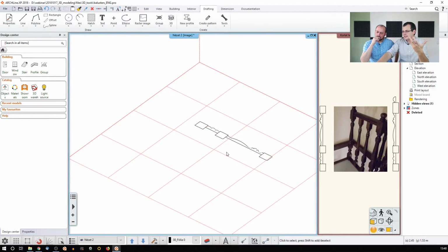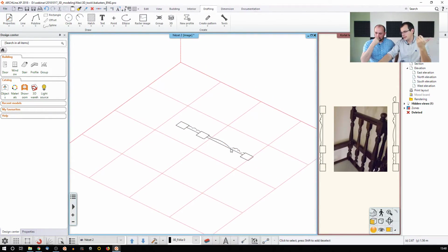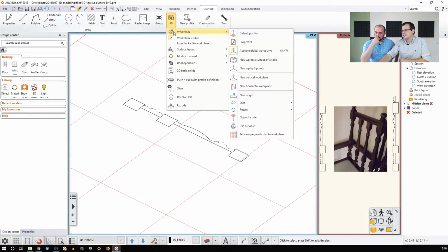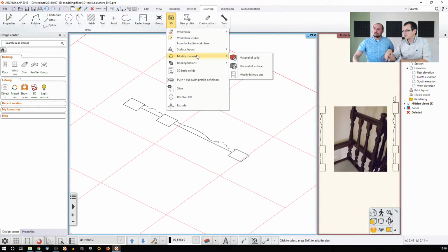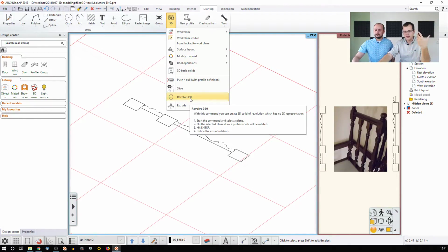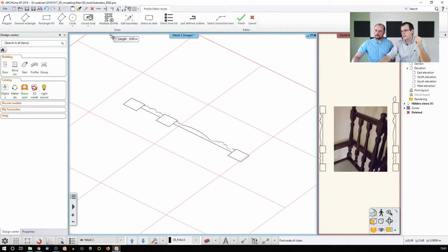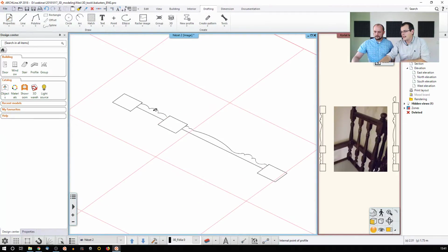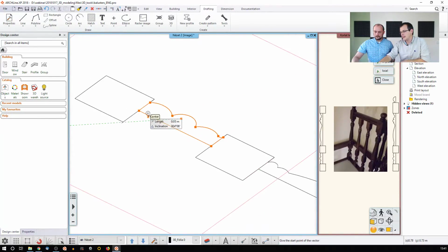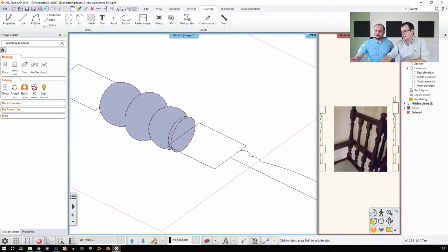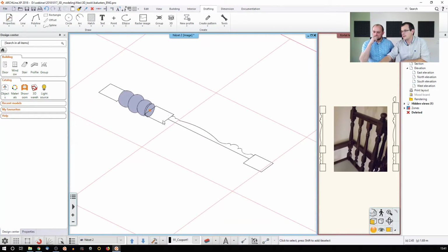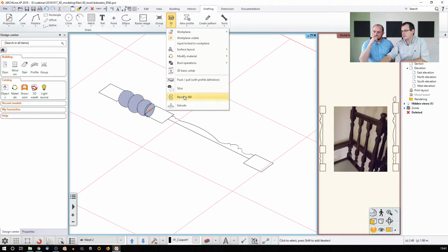And now the next task is to turn this into a 3-dimensional object. And I do this with these tools, but instead of sketching the boundaries, I will use the fill recognition tool that you use. That's right. I have this Revolve 360, which is going to create solids of revolution. Here's what I do. I hit close loop, and I click into the chain I want to use, and then I just define a rotational axis. I perform the task, and I end up with a revolved shape. I use the same thing again.